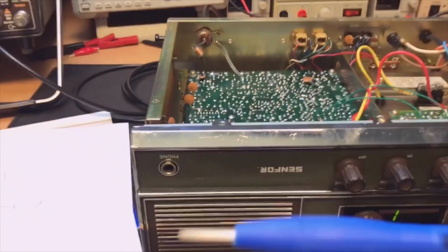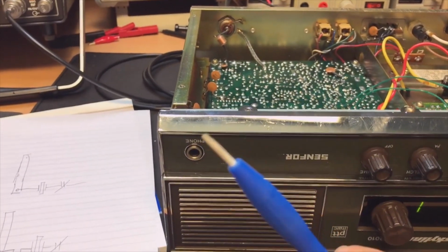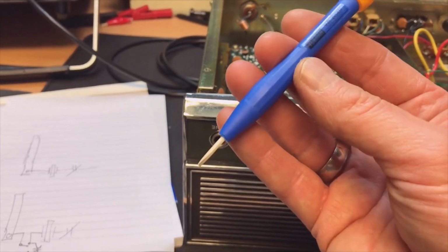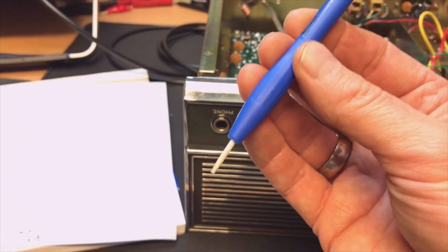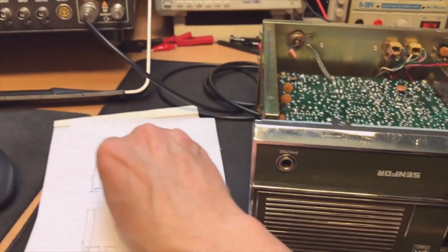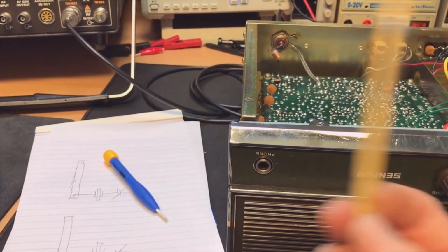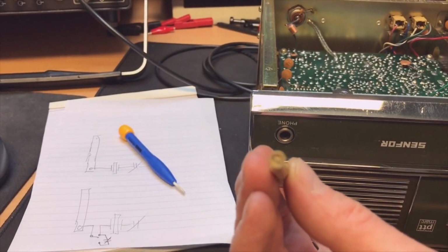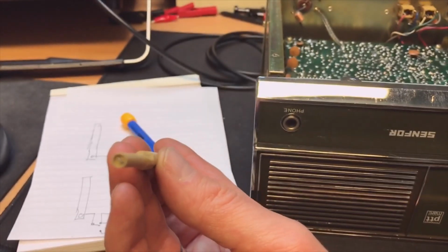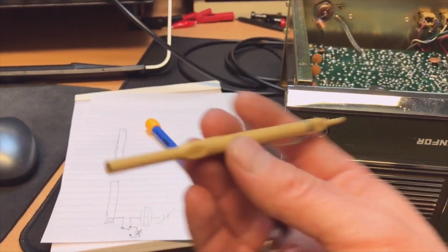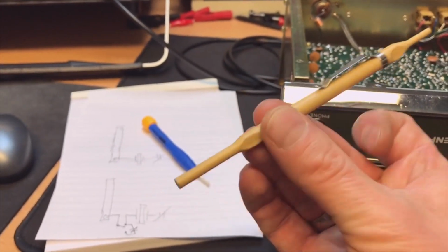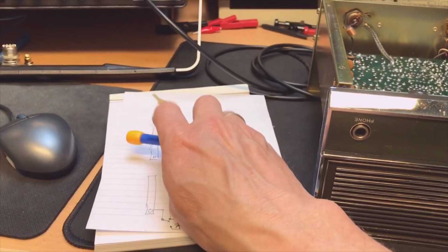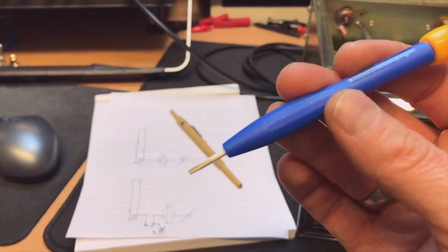To adjust, you cannot use the normal screwdrivers, because if they have metal, they will influence the capacitor, so I use these things. These are now available. It's ceramic and plastic, so that doesn't influence too much. And 20 years ago they had the nylon. The nylon was not that strong, so they put a very little metal in the middle, to influence it as little as possible. This one in that time was great, but of course because it is metal it will influence, so now I'm always using these ceramic ones.